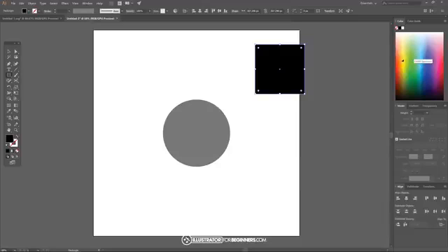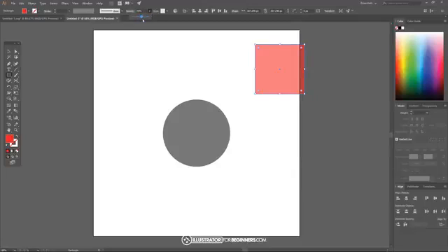And I'm just going to make the color of this red for now. And again, I'll take the opacity of this and bring it down in half. And what I want to do now is come over here to the Select tool, and I want to hold Alt on the keyboard and click and drag on that rectangle. And that's going to create a duplicate copy of it.